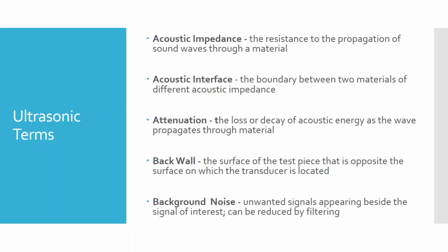And then we went on to talk about how fast the sound travels and what affects the speed of sound in a material. The density, right? And density changes with what? Temperature is a big one. Pressure on gases, but we're mainly looking at solids in this case. So temperature can affect that, and it's not always positive or negative, right? Water does a really weird thing where it gets less dense as it turns into a solid. Most materials get more dense as they become solid, but certain crystalline structures can change that.